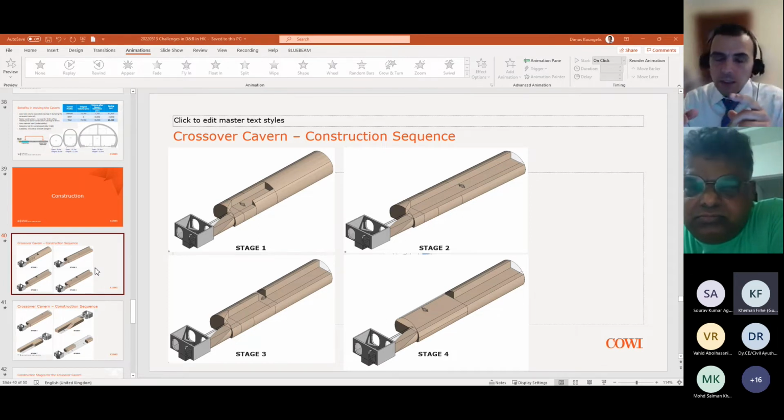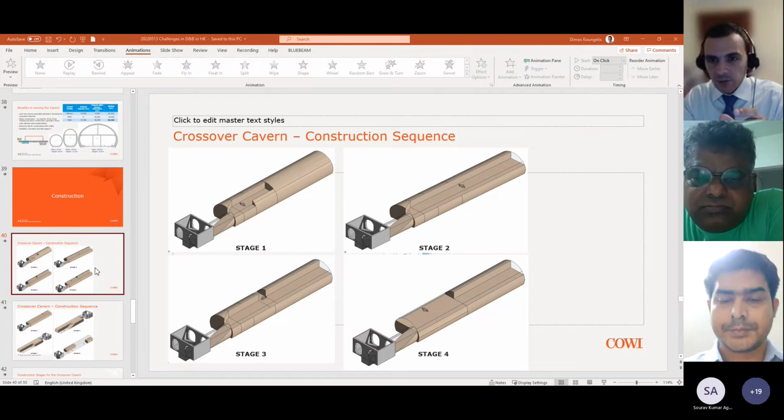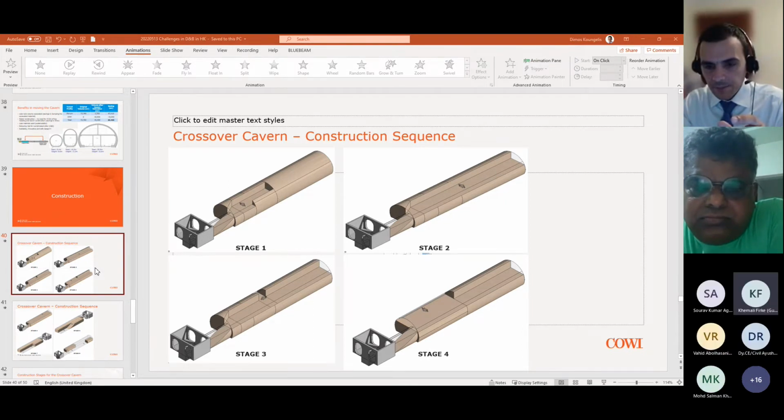And also on top of that, the thickness varied depending on the rock conditions or the anticipated rock conditions. So we had the support classes, and for the better support classes, we had a certain thickness. And then for the worse support classes, the thickness of the lining would increase, and on top of that, we may have had some reinforcement in the lining as well. Because there were so many profiles, the thicknesses varied significantly.